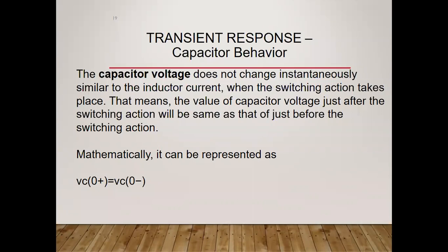Similarly, how much current flows through the capacitor is also important. But while we are learning the fundamentals of the storing elements, L and C, we are always interested in the current flowing through the inductor. For the capacitor, we are not interested in the current; we are interested in the voltage across the two plates, because we treat the plates as two parallel plates with a dielectric. We are interested in the potential across them, the plus and minus battery symbolic representation. So always remember that for the capacitor, we are interested in measuring the voltage.